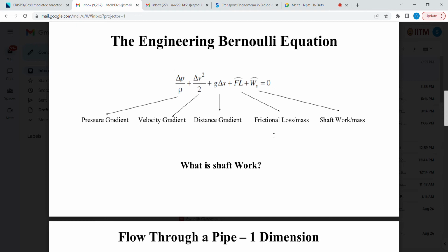There are different types of compressors. I'm not going to go into it, but what I want you to understand is that there is an inlet, there is a volume element in which the air gets compressed, and there is an outlet where the high pressure air comes out. So how is this? You cannot convert a low pressure fluid, in this case air, into a high pressure fluid. You have to do some work on it, right? And that's where the compressor comes in. That's where the air end comes in.